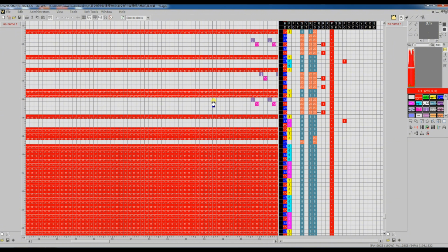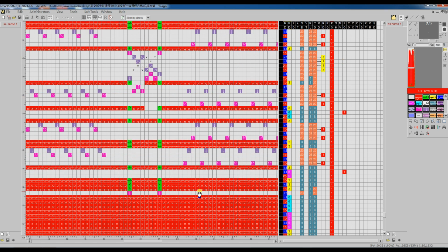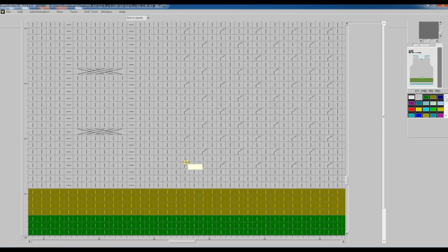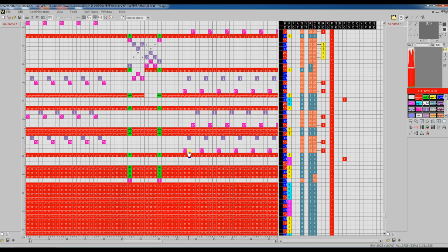We can see the stitch and machine movements for pointelles and cables here. At the sides of the cables, we have back stitches knitted. Pointelles are created by transferring the stitch to the adjacent back needle and then transferring straight back to front. The back needle bed, racking direction, and distance can be viewed here.